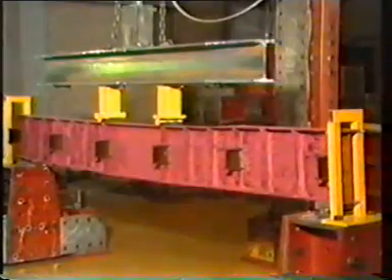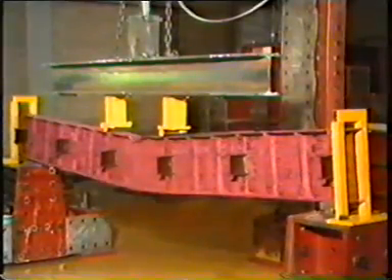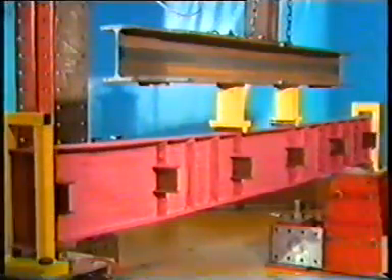A panel of the main girder is limited by the upper and lower flange of the main girder and two cross girders. A test on such a panel in pure bending: buckling of the web in the central panel occurs, including local flange buckling in the final stage. The same test in shear in an end panel.